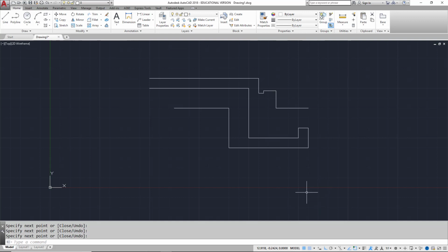It's important to remember that you want to use settings for grid and snap that make sense. If I was doing an architectural drawing, maybe a layout of a factory, my grid might be something like 4 feet. Where I'm working with a large facility, it wouldn't make sense to have a grid that was a half of an inch on something that large.